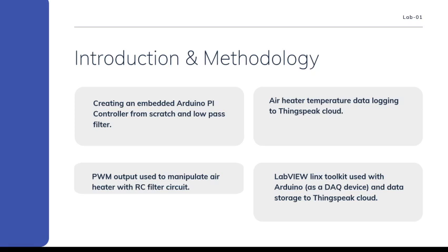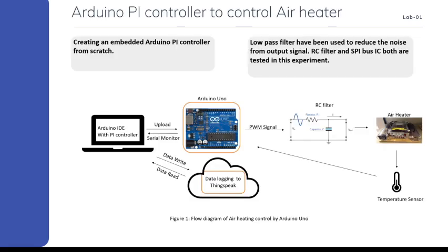In that case I've used the LabVIEW Linux toolkit, which will manipulate and control the air heater. I have also used Arduino with LabVIEW as a DAQ device, since the NI hardware is expensive, so we are trying to overcome this expense. And here is the Arduino PI controller to control the air heater.